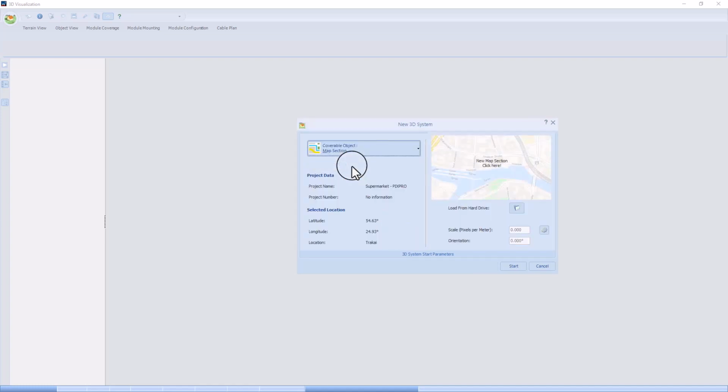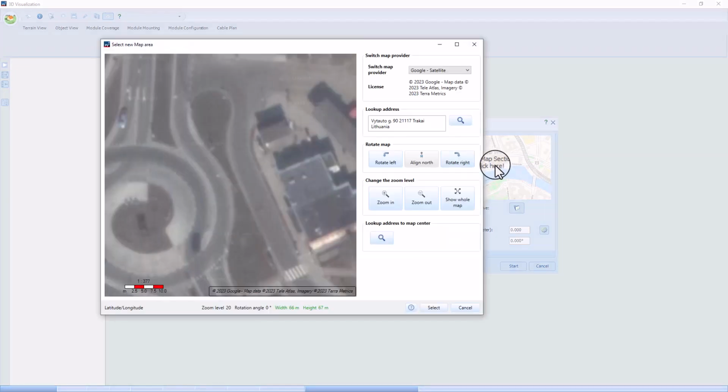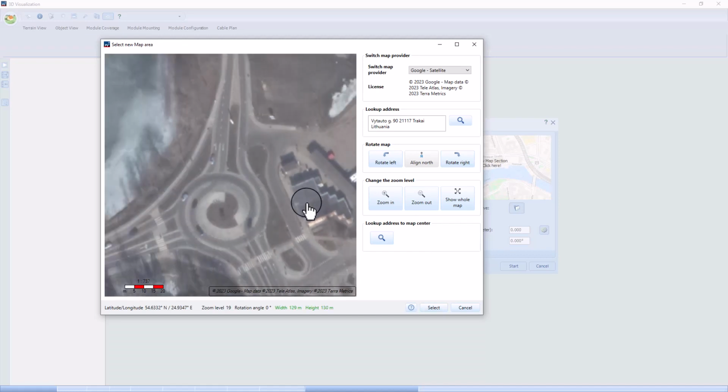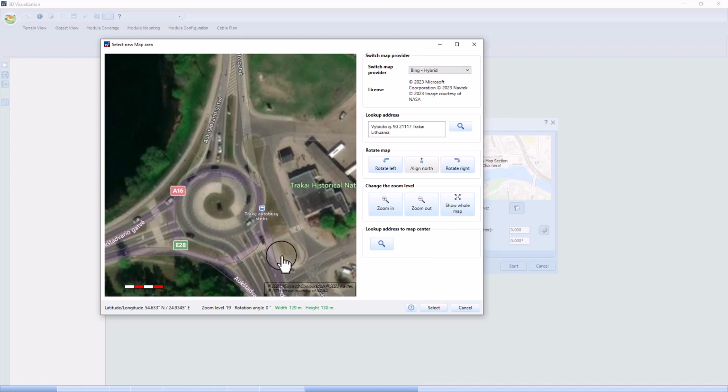The map is optional. It depends if you have nearby features such as trees or neighboring buildings that you wish to add separately to the OBJ mesh. You can use maps from online providers. So by clicking on the section of the map here that says click here, you get a choice of those providers. The map we're looking at right now looks very pixelated and outdated, so we'll have a look at some of the other options. Maybe slightly better, but it's still actually outdated.